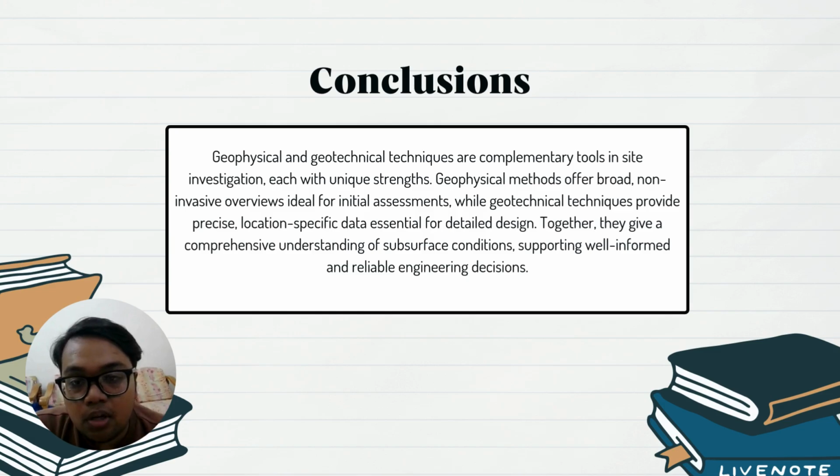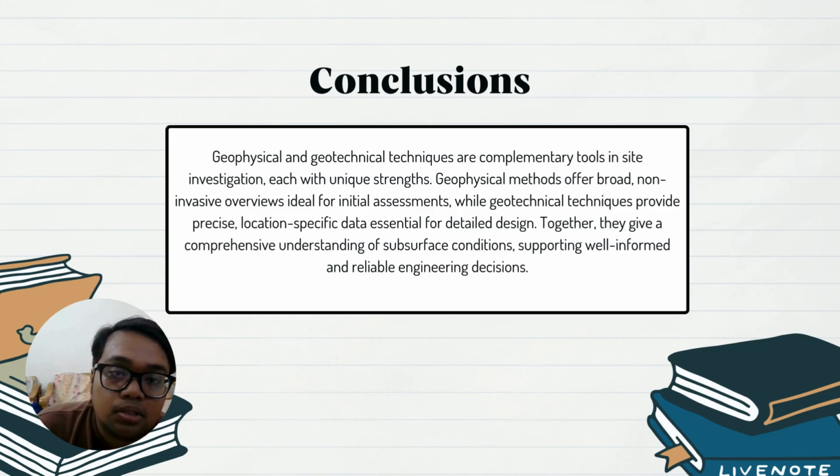So from the differences of these two methods and the advantages and disadvantages that we get from these two techniques, we can conclude that geophysical and geotechnical techniques are complementary tools in site investigation, each with unique strength. Geophysical methods offer broad, non-invasive overview, ideal for initial assessment, while geotechnical technique provides precise, location-specific data essential for detailed design. Together, they give a comprehensive understanding of subsurface condition, supporting well-informed and reliable engineering decisions.